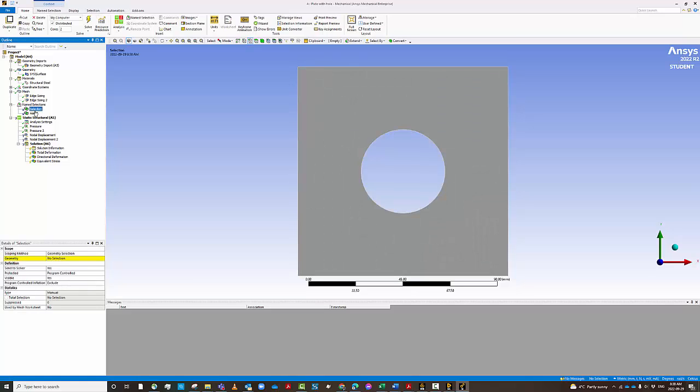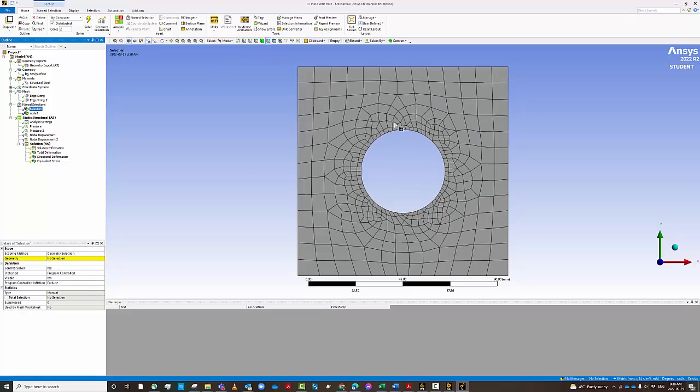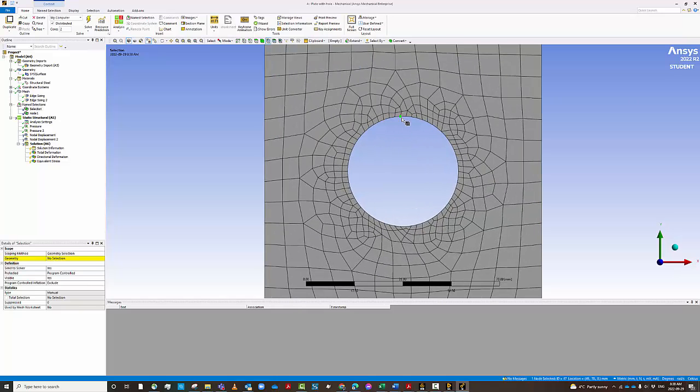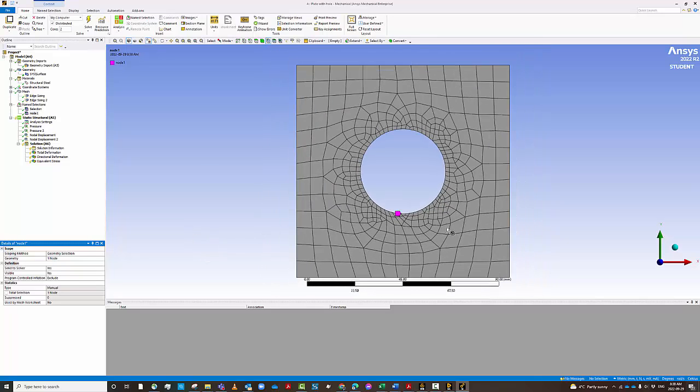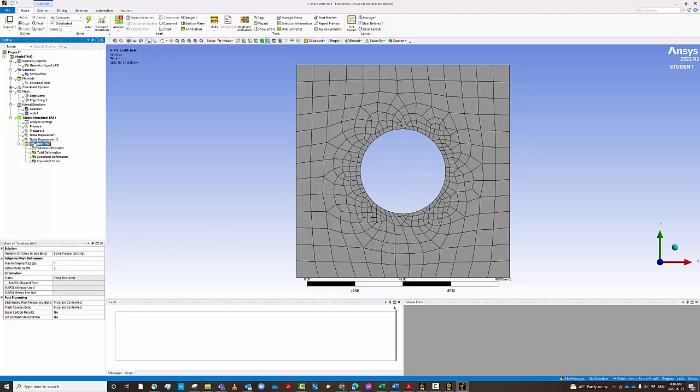So again, I have to go here and I have to pick a node and then you select this node, right? Select a node here, you can zoom of course on the node, right? And you can go to apply and then go to the next one. And as you can see here, this is now X because this is a sheet of this node that the ANSYS doesn't know what it is. Now if I go to this node, okay, and then you can go here and apply, everything is corrected. Okay, for that error, you might go ahead with only one node and it will save you. It might be 2 nodes, 3 nodes, depends on the geometry and what exactly you are doing. Okay, so solve.